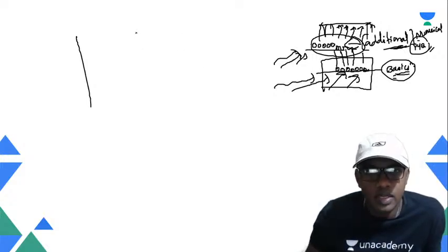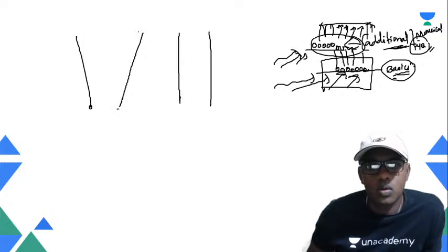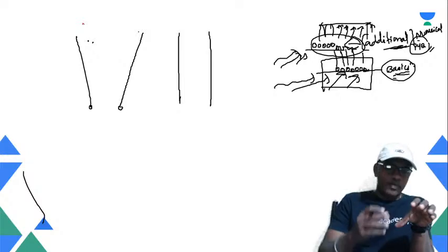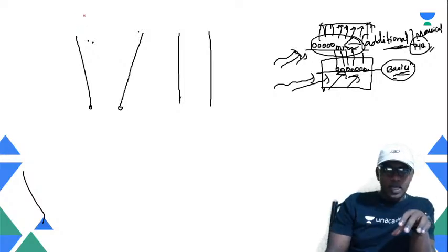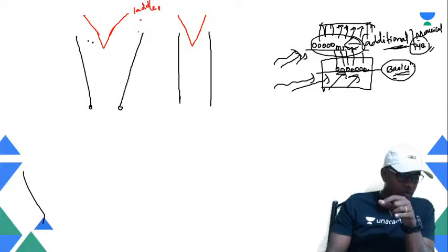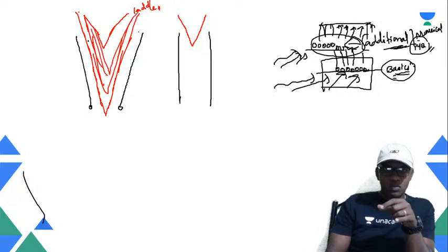Now, sir, what is the need? This is the need, sir. If the sprue is straight versus if the sprue is tapered, the benefit is this: when you pour the molten metal, if you assume a tumbler and you pour the water, you know it will take this position, right? So when it is being poured from a ladle into the pouring basin through the sprue, it will pass in this direction. So remember, it just falls in like this, correct? This is how it will fall.